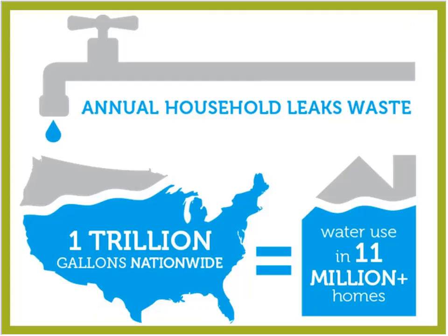And so working with your clients, especially on an existing home, to identify any leaks and put a scope of work together to repair those can help make a huge impact on reducing water waste. Some of the simple ways to do that is making sure all the water is shut off in the house, taking a photo of the water meter, and then waiting 2 hours and taking another photo and seeing if it's moved. You can also put food coloring in the toilet tank and then see if it's drained into the bowl. And those are some simple ways, but you can check out Fix a Leak on the EPA WaterSense page as well.